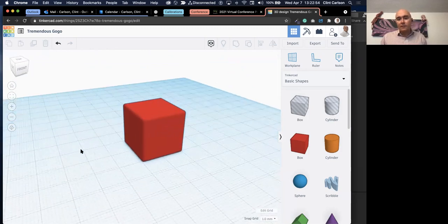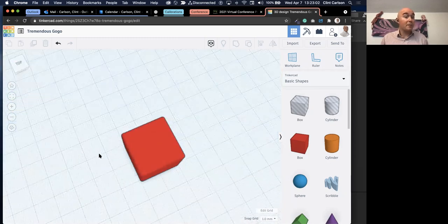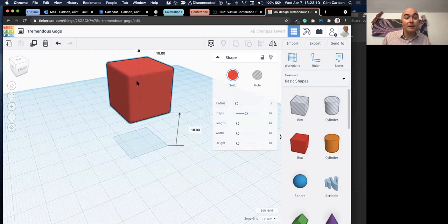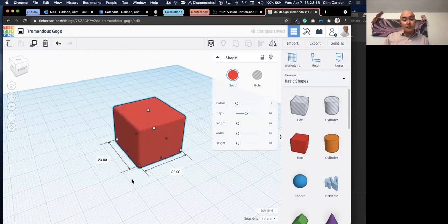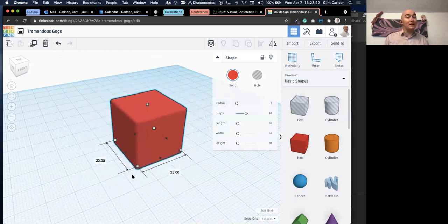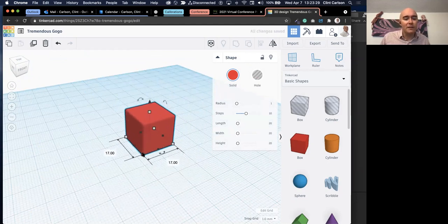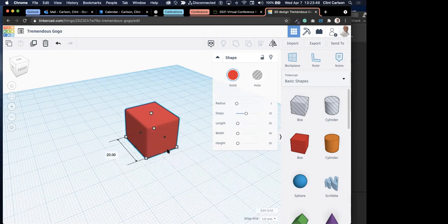That gets us going. All right, so now we need to actually define which side is 1, 2, 3, 4, 5, 6. And we'll do this through 3D modeling. So our next piece, I'll grab this die, and I can drag this around on the XY axis, or I can raise it up and down using the arrows. I also get these fine tools in here that will allow me to grab a corner and drag pieces out. If I hold down Shift, it'll constrain that to keep that cube shape. Similar to resizing a photo, if you're familiar with that, where you hold down Shift to keep the dimensions of that image in place. Same thing applies to 3 dimensions. So those are those white boxes, and then we've got these little black boxes that are centered at these intersections. So we can grab those and really cleanly extrapolate, drag those out.